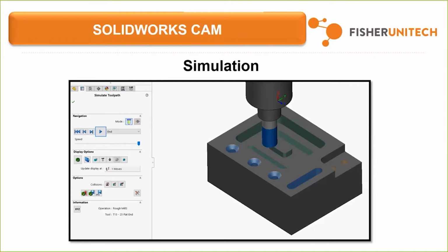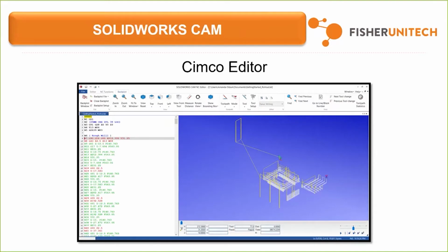Also within SOLIDWORKS CAM, you get simulation so that you can simulate your toolpath and see if there's any collisions going on, see if the toolpath is acting appropriately, make sure that the shank of the tool, the cutter of the tool, and the holder of the tool are not colliding, things like that. You also get the Simco editor, in which you can simulate the toolpaths, and you can also go ahead and edit your G code within the Simco editor.